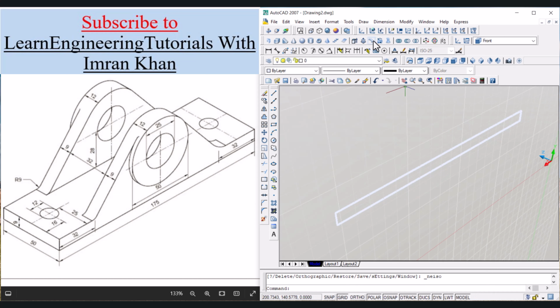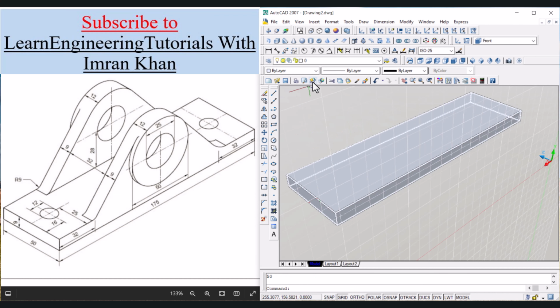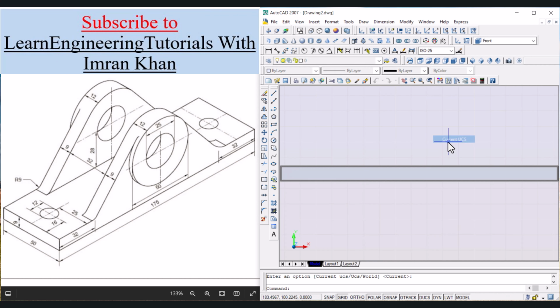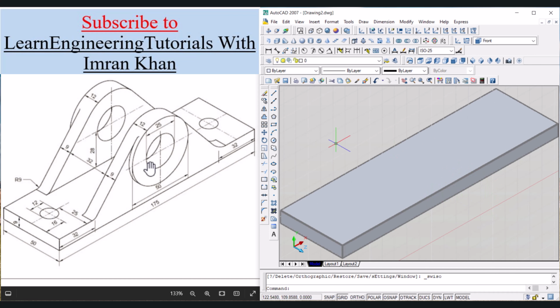Now click on press pull, bring the cursor over here, click and give the thickness of 50 mm. 50, enter. Click on view, click on 3D views, click on plane view and current UCS. Now click on southwest isometric view. So here in the front view we will draw these objects. So for that click on front view now.